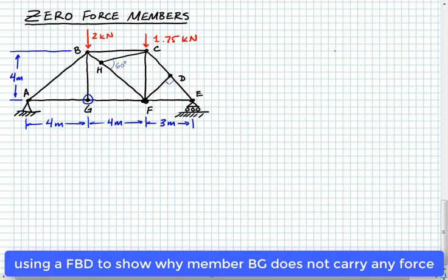All right, so here's the joint at G, and if we look at that, at G, we might have some forces that are due to member AG or due to FG. Okay, so we'll put those on here. Call that TFG, and we'll call this TAG. All right, and then we'll have this other force that acts upward right here, and we'll call that TBG.